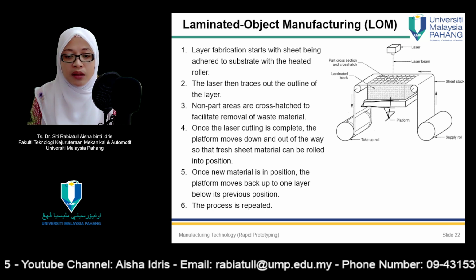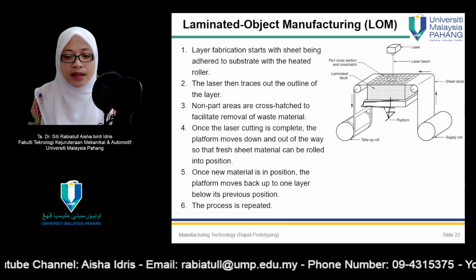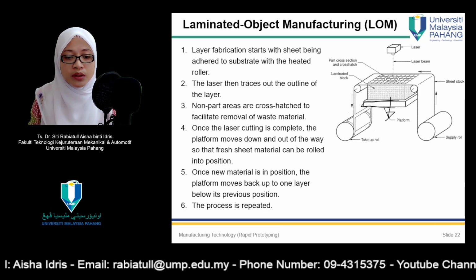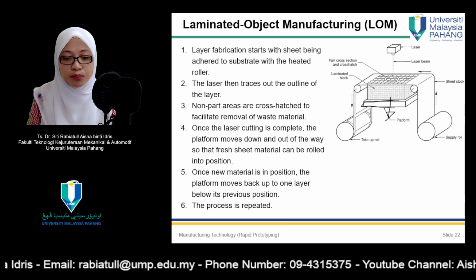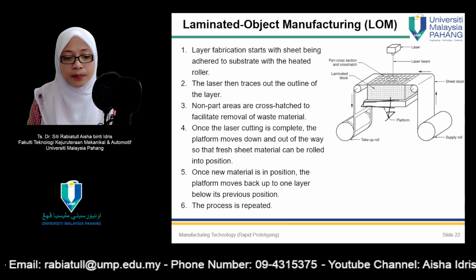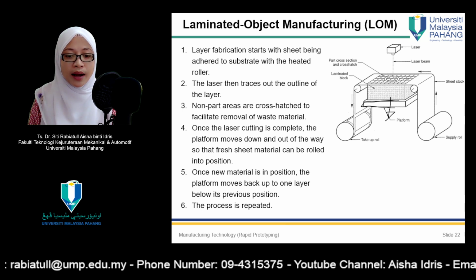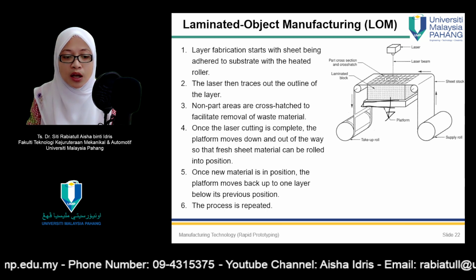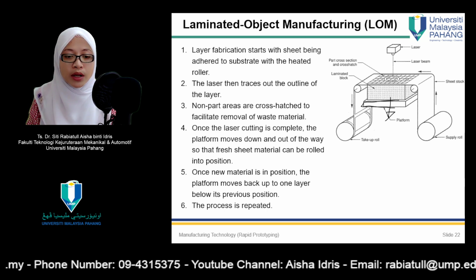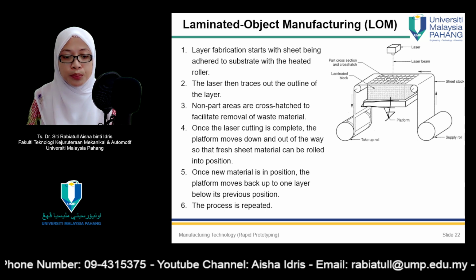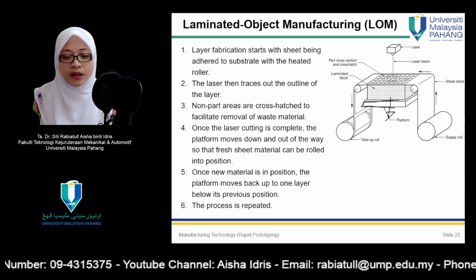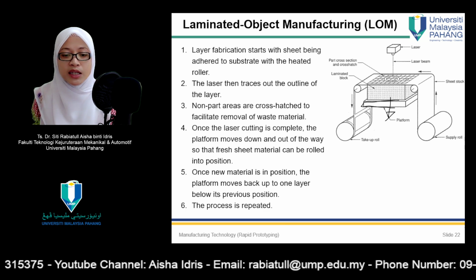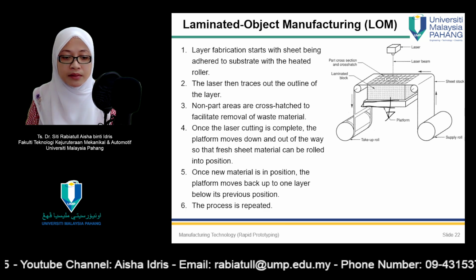Number three, the platform holding the stack is lowered and the sheet stock is advanced between the supply roll and take-out spool for the next layer. The platform is then raised to a height consistent with the stock thickness, and a heated roller moves across the new layer to bond it to the previous layer. The height of the physical stack is measured in preparation for the next slicing computation by LOM Slice software.